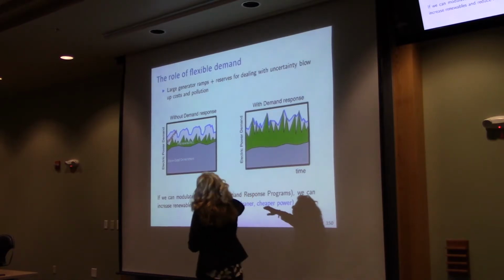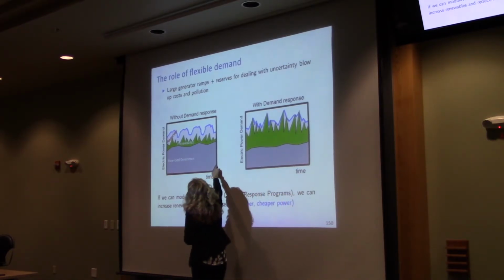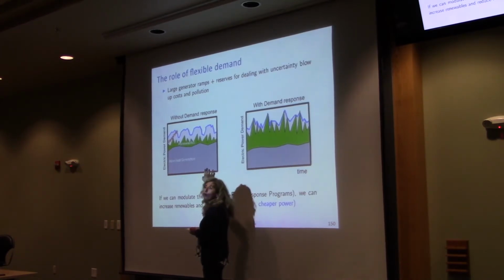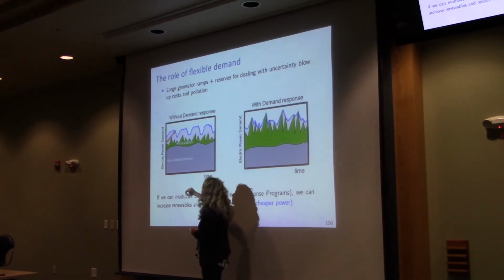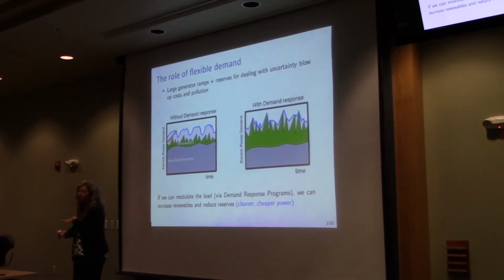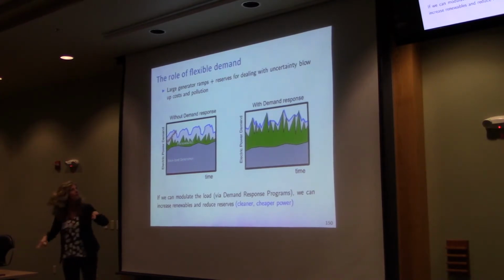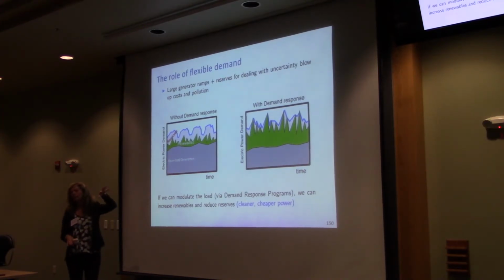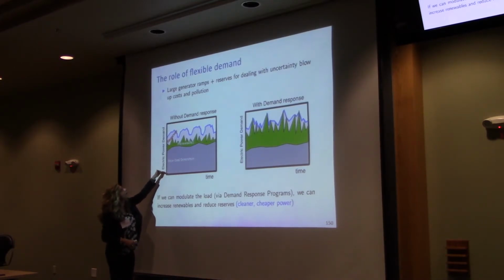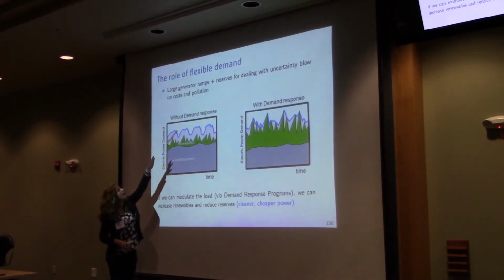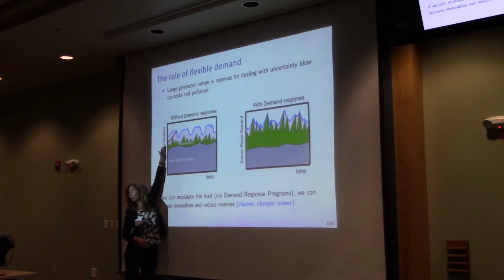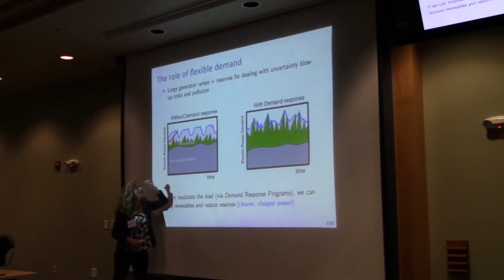Now you have a base load generation, and nuclear power plants and coal power plants are really good at it. Gas power plants can do more stuff. They're actually really nice because they can go up and down fast, but nuclear and coal actually are pretty slow. So you have to have a kind of flat demand for them. So what you do is, the amount of electric load you require is like these mountains that are above a big amount. So the big amount you cover with the base load generation.